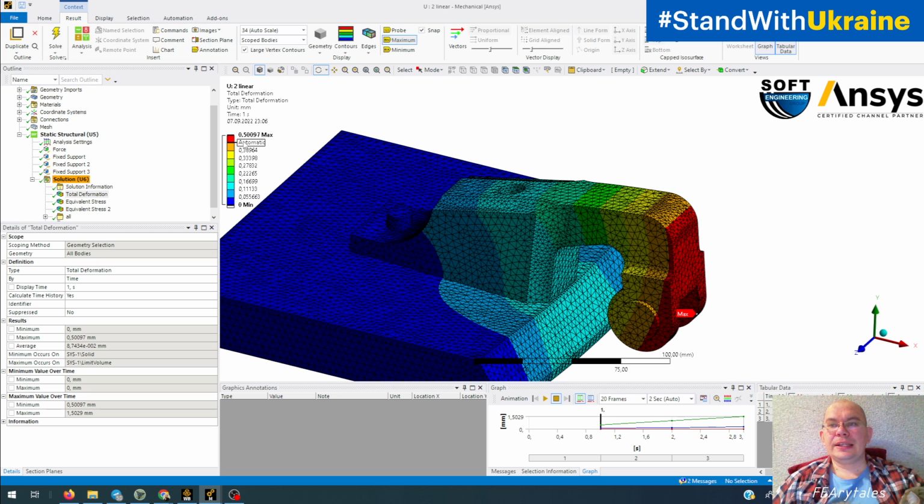So we have 20% of difference with the same mesh size but with quadratic element, and we have less deformation than with the default, very coarse mesh, but that default mesh was created with quadratic element, and this very good mesh created with linear elements, and we have 10% less in deformation.